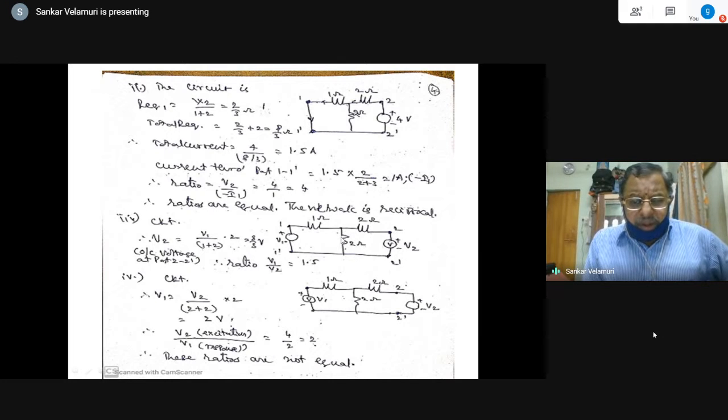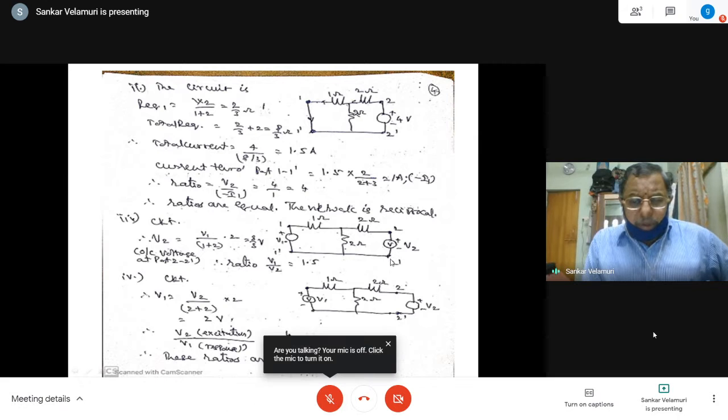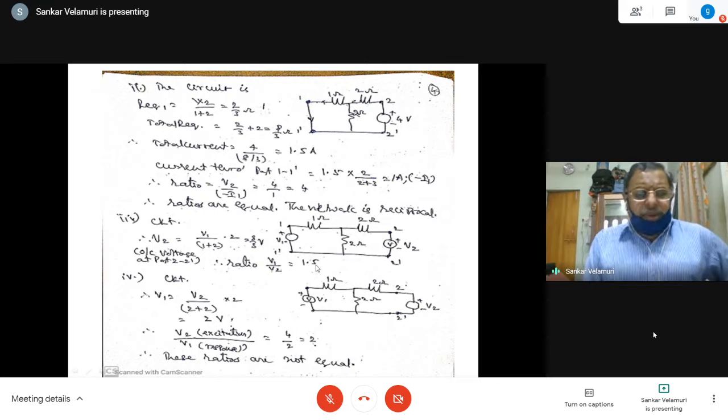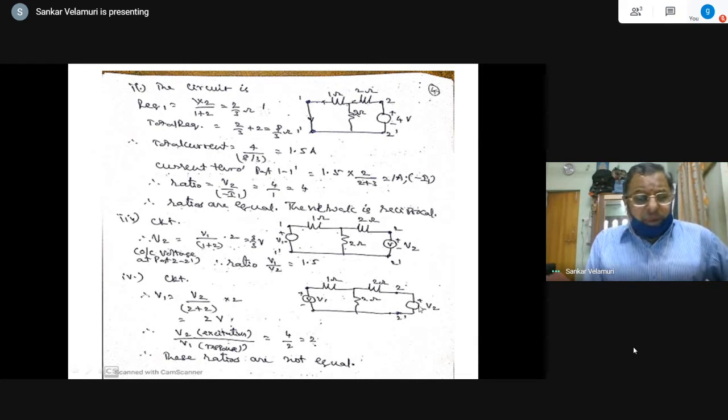These two are connected. So this resistance is connected across the port 2. So that ratio of the voltages can be used at a later stage as the voltage gain. Or similarly, when port 2 is excited with a voltage source, you want to get the V1, which is the voltmeter, that is the open circuit voltage at port 1 dash. So now you can see this is open as far as this circuit is concerned, because no current can flow through this particular one, port 1 dash, because you are measuring the open circuit voltage.